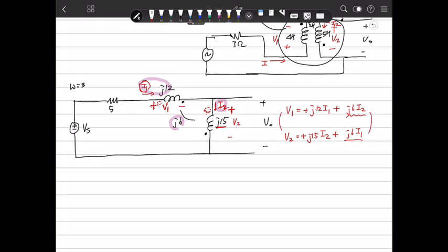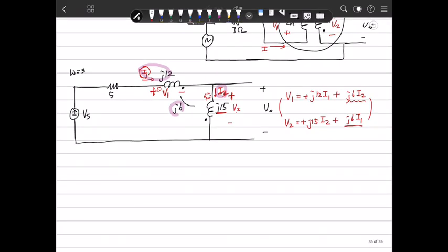So we get it. Then the remaining thing is to apply the equations to solve this circuit. I'd like to solve this mesh in this manner. Therefore, minus Vs plus 5I1, plus V1, plus V2 is 0. So that's it.